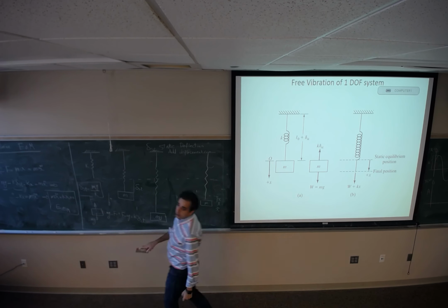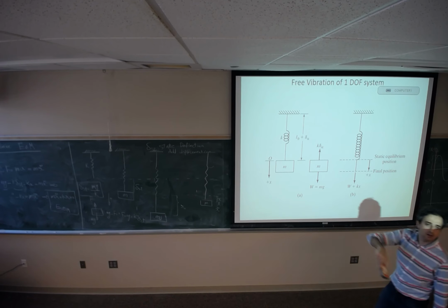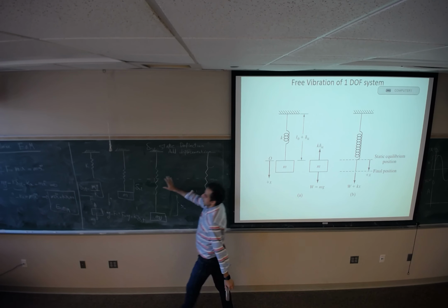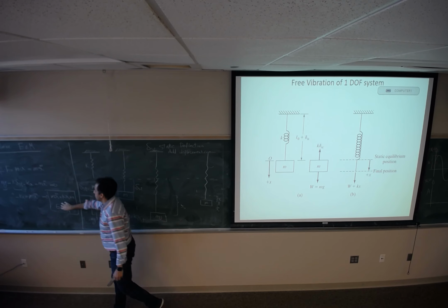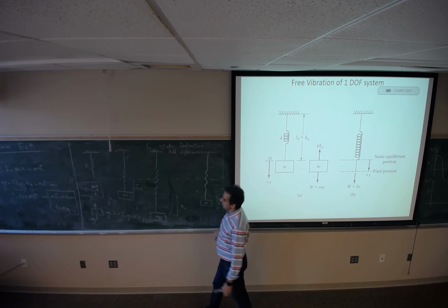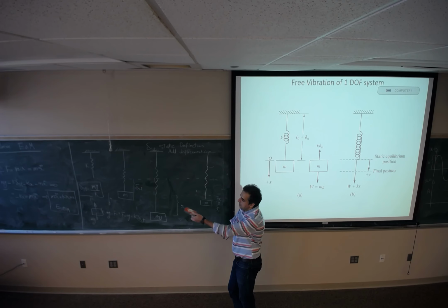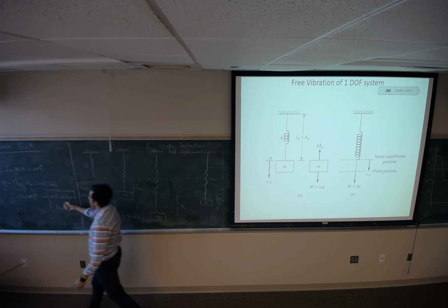Good? So if you look at the equation of motion, no term of static deflection is showing up there. So the equation of motion is not dependent on the static deflection, and the weight of the mass. See, there is no mg showing up here.